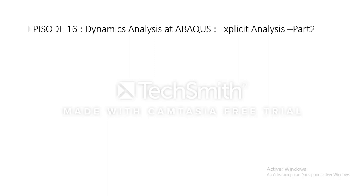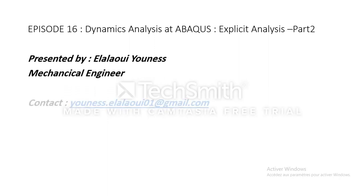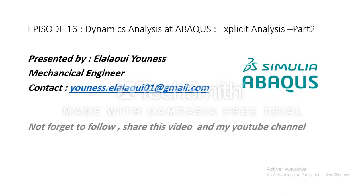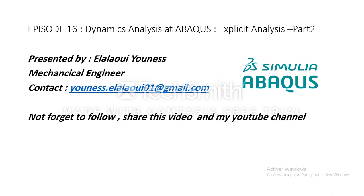Hello everyone, in this video we will discuss ABAQUS with the explicit method. The objective is to have a good idea why we use this type of explicit analysis for many dynamic problems compared to the standard method, and to estimate the time of stability used as a principal property of dynamic analysis.